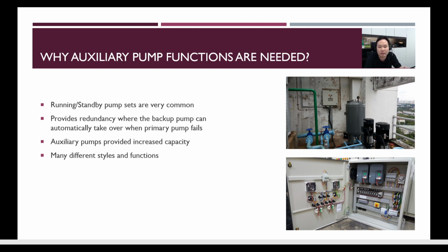There are many different styles and functions depending on each manufacturer and panel designer. Some people design it using a timer, some prefer a lead lag, some prefer a latching relay, and things like that. So today the main point we'll be talking about is the auxiliary pump, especially with regards to the ATV310, and to some extent this is quite similar to the ATV610 as well.